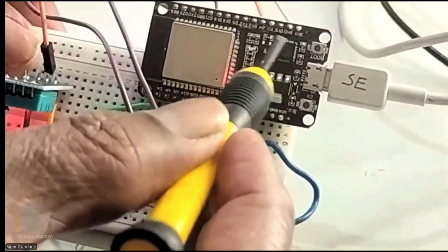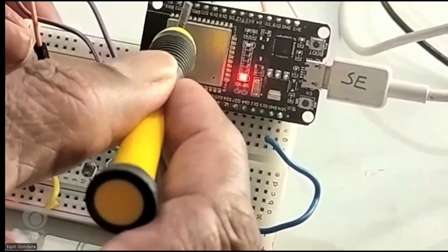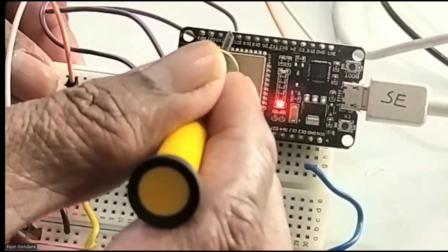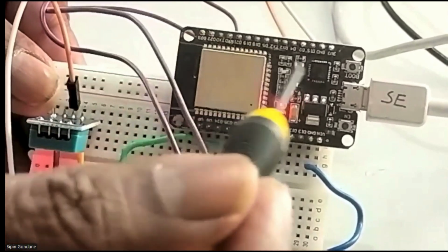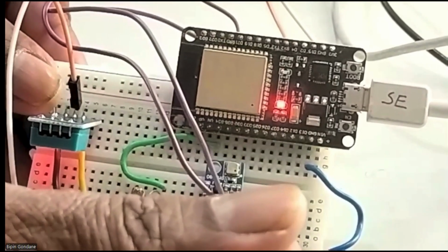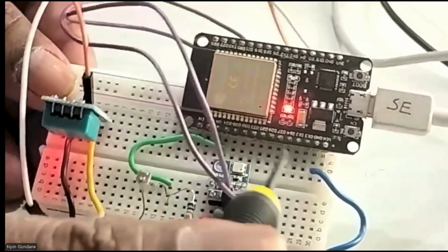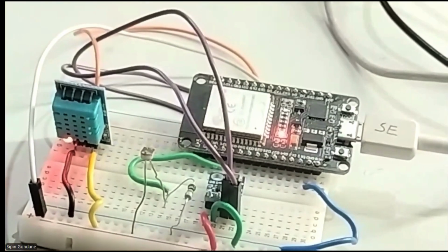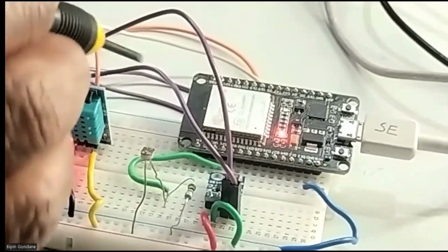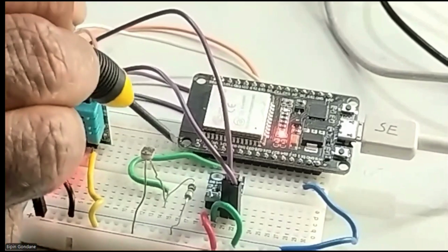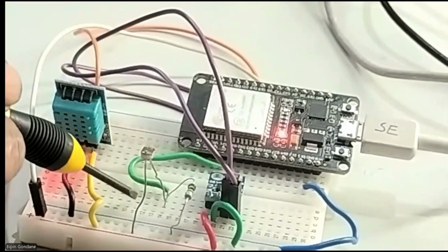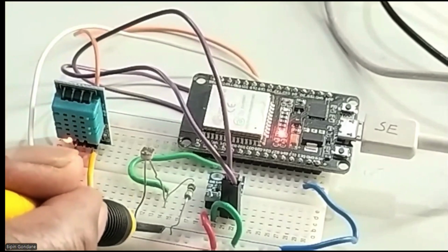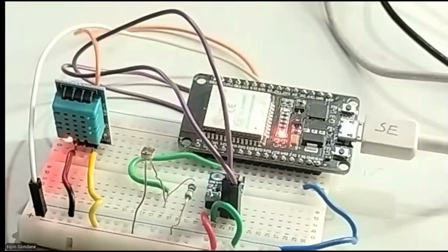Then you have SCL and SDA, which are connected from this side, to pin numbers D22 and D21, which are on this side, and which go to the BMP180. These two wires I have connected to the BMP. For the LDR, I have connected one green jumper wire directly from pin number 34 to the LDR, and from there I have connected one 10 kilo ohm resistor to ground, because it's a pull down resistor.